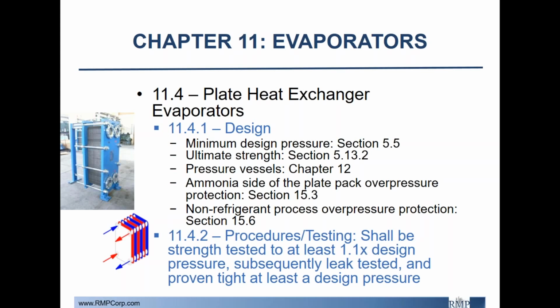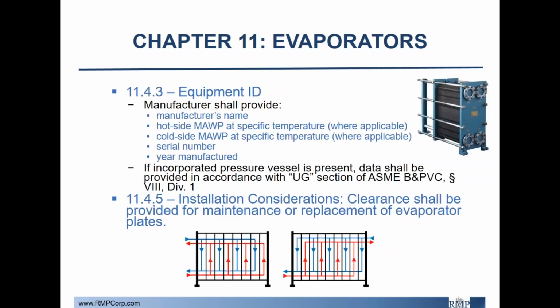On the non-refrigerant side, the inlet and outlet lines of the plate packs, if they're isolated, must be protected. So that is something that calls out without an exception. And again, looking at the pressures, the procedures and testing section, the strength test, the leak testing, and the proven tight to design pressure are the same as some of the other pieces of equipment.